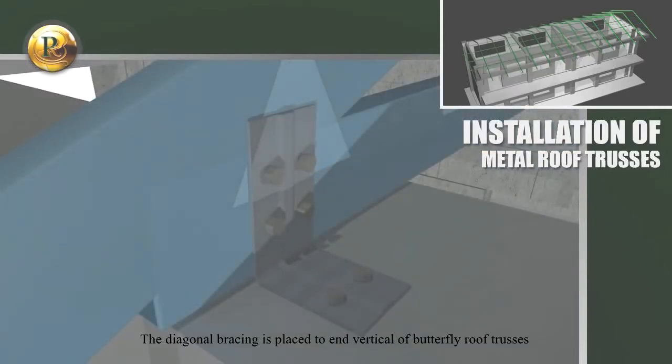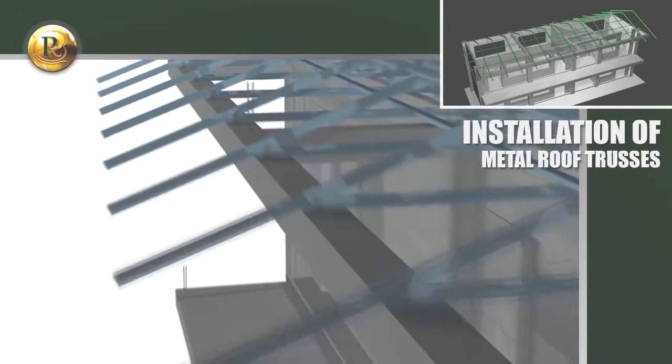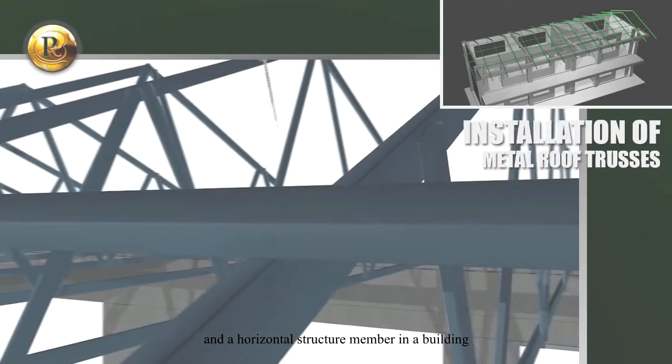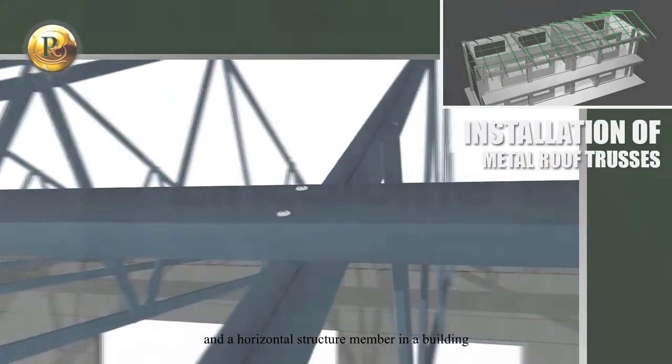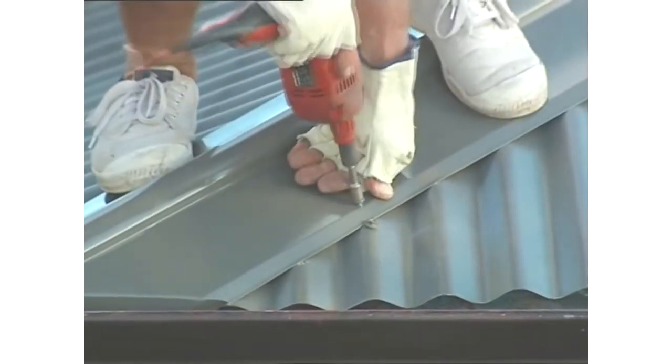The diagonal bracing is placed at the end vertical of butterfly roof trusses. Purlins function as a form of support for rafters and are horizontal structural members in a building. They are used to increase roof spans without the need for increasing rafter sizes or compromising wall stability.